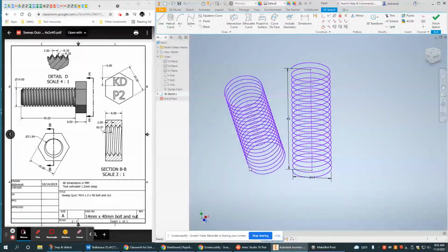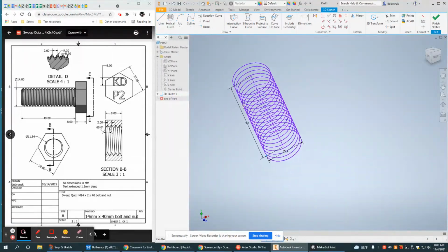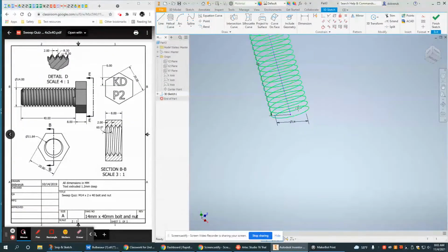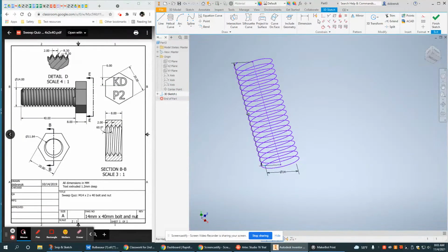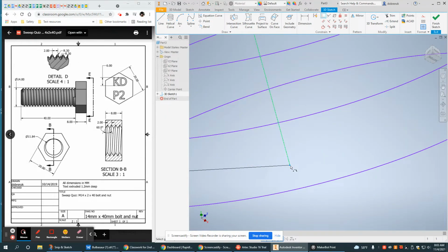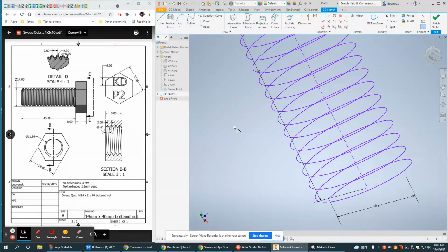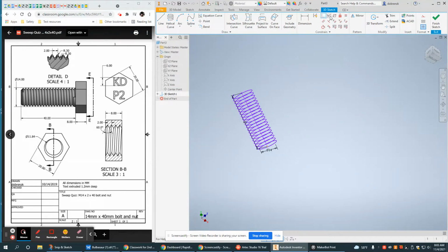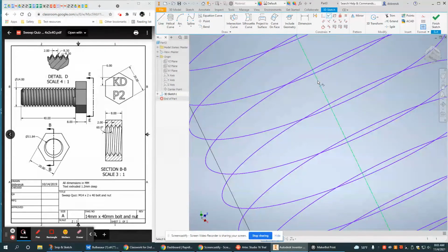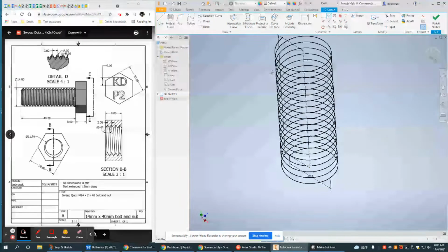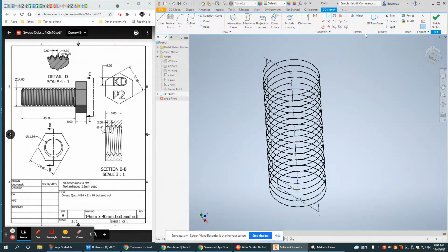But I can see that despite my effort to try and use the origin, that didn't work. But I can easily go back and do that. I'm going to select the starting point of my center line, and then I'm going to click center point. I'm going to do a collinear because I want to take this line and put it on one of my axes, which I think was the y-axis. So there we go. Fully constrained now, ready to rock.